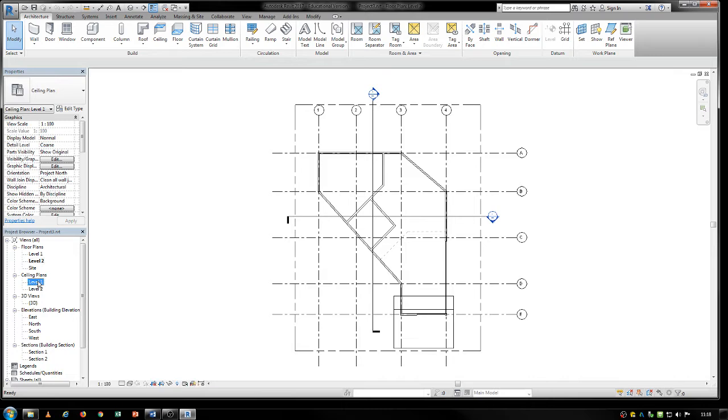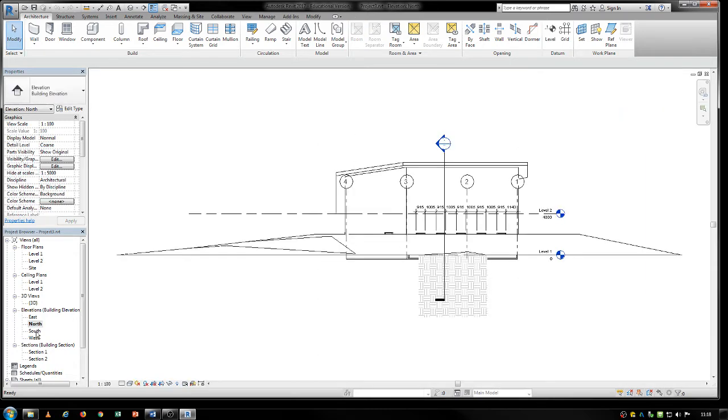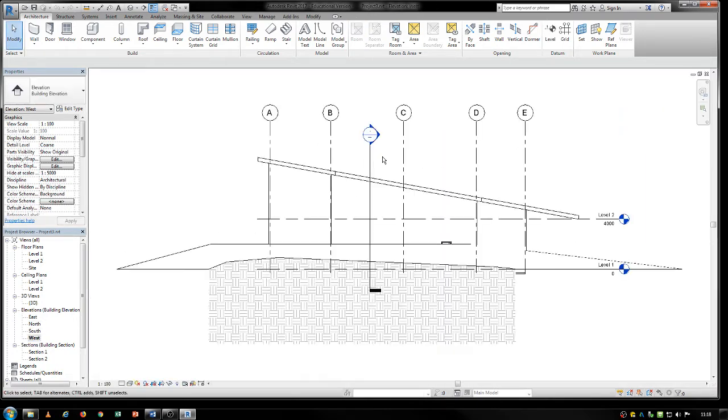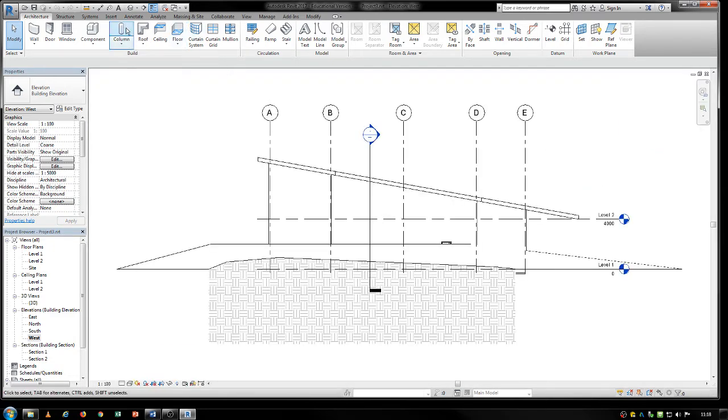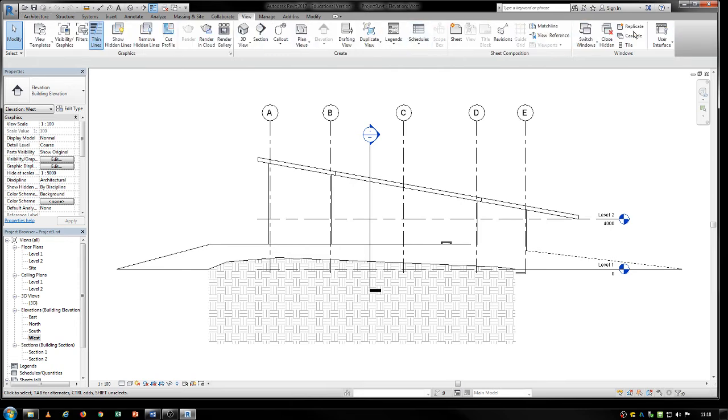So when you are in your Revit project and you have all these views open, you know that you have a lot of windows open. So it's not views that you're opening, these are actual windows that you open. The way to work with them and manage them is under View, and then this last piece over here where you can switch between windows through this menu. So it gives you actually the names.